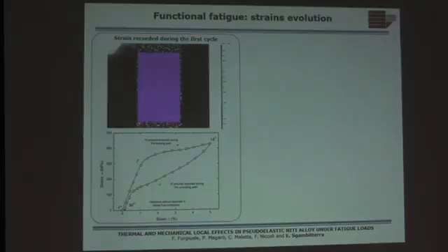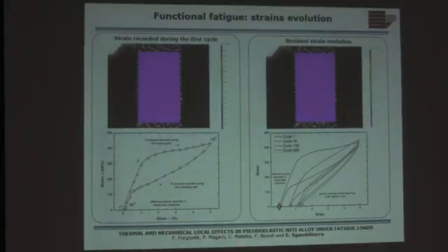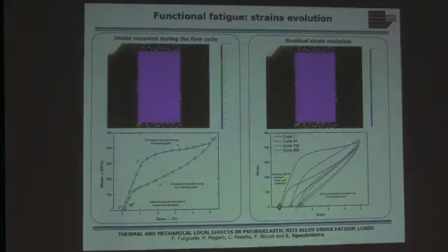So, if you want to study the evolution of the residual strain, you can easily read the stress strain response after 1 cycle, 10 cycles, 150 cycles, and so on. As you can see, there is a ratcheting effect, accumulation of strain, and typically it tends to stabilize after 150 to 200 cycles, as you can read also in literature.